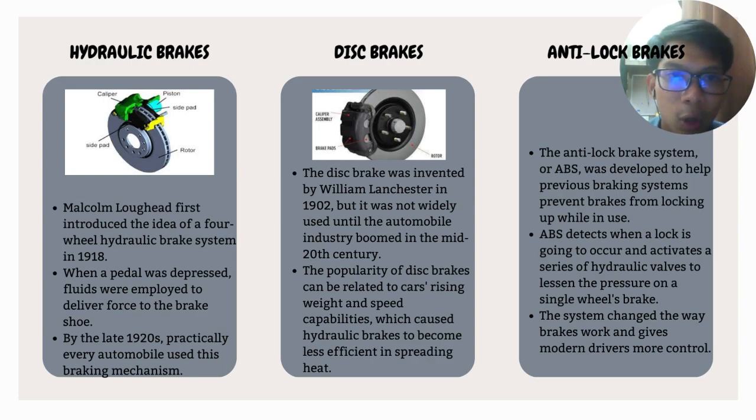The last one is the anti-lock brake. The anti-lock brake system, or ABS, was developed to help previous braking systems prevent brakes from locking up while in use. ABS detects when a lock is going to occur and activates a series of hydraulic valves to lessen the pressure on a single wheel brake.